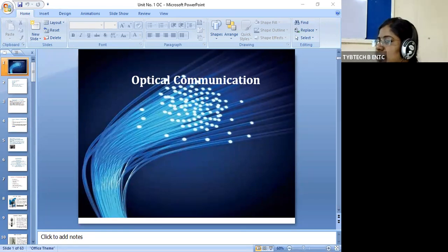Now less attenuation. So attenuation meaning you were asking. The word technically stands for the meaning as loss. Now there are different types of losses: scattering loss is there, bending loss is there, absorption loss is there. By considering all the losses present in the optical fiber, whatever total loss you are going to consider, that is denoted by this word called attenuation. So attenuation consists of the impact of all the losses involved in the optical fiber.